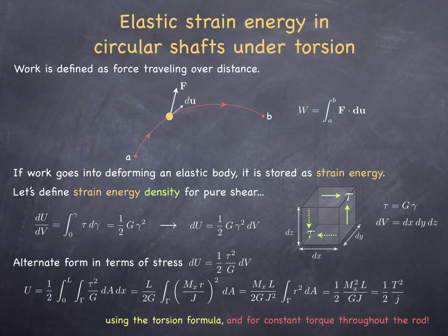You have to go back to the integral towards the left and carry out the integral of mx, the internal torque, more carefully as it varies through the cross section. Now that we know how to compute the internal energy, we can use it as part of Castigliano's theorem.